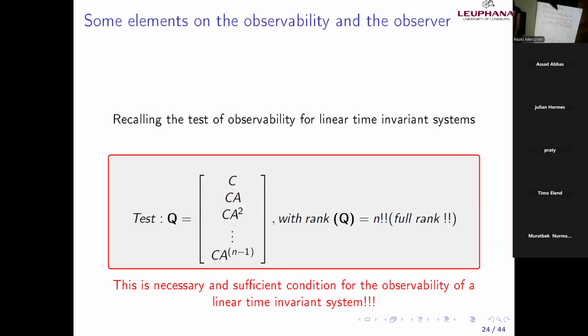This test is basically implemented now. Full rank means connections everywhere between the states. This is the practical meaning. Of course, rank is the mathematical concept related to the number of independent columns, for instance, or rows, of a matrix. I don't know if you remember my lecture. But anyway, practically it means MATLAB helps us to see that we have connections everywhere. This means it doesn't matter what I measure, I observe all the rest. There is no unobservable part.